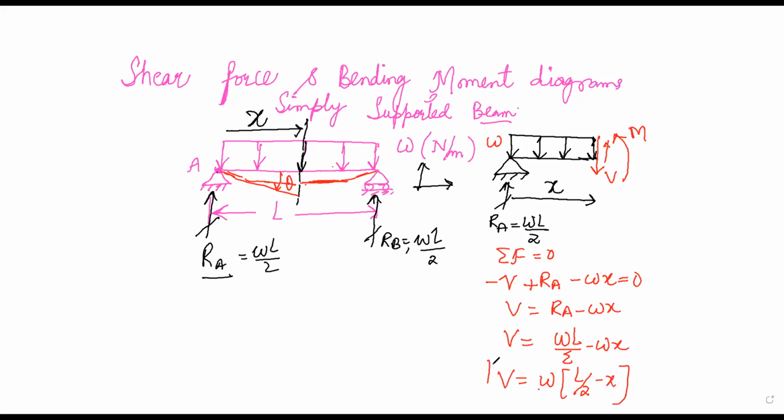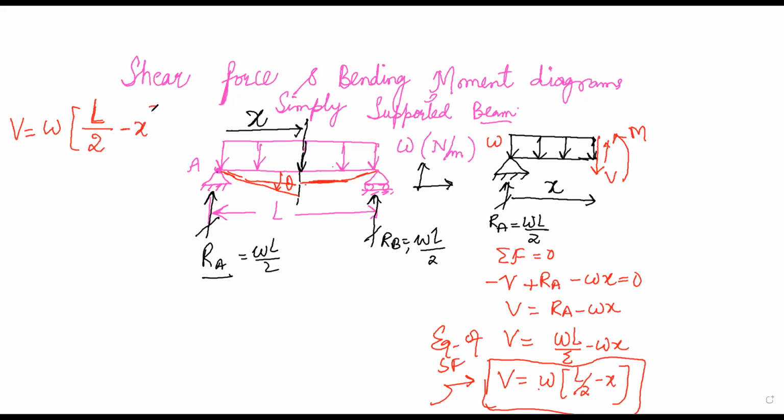This is shear force. This is how the shear force varies. This is the equation of our shear force. I will write it here. The equation of shear force is V is equal to W into (L by 2 minus x). Okay, this is the equation of shear force.